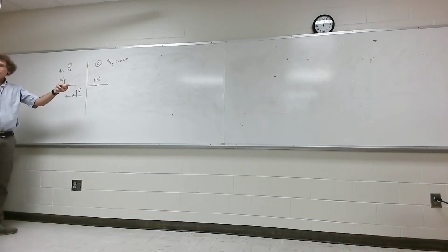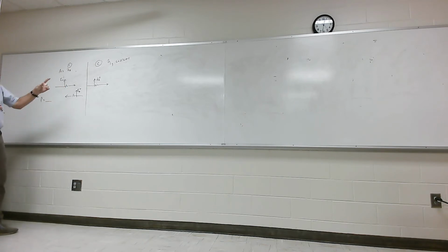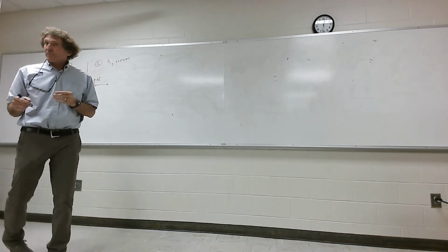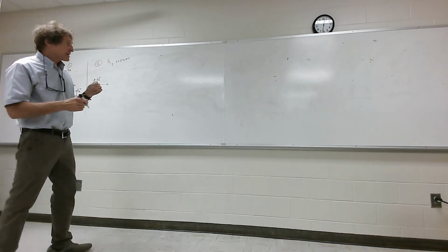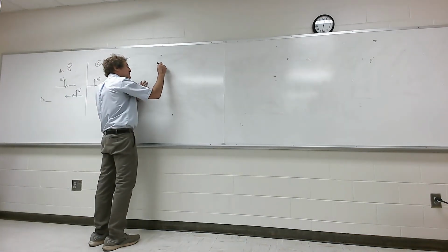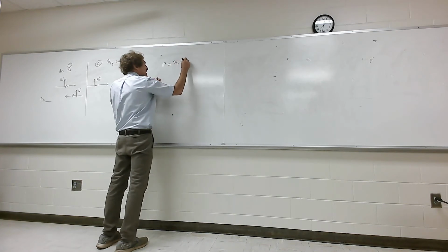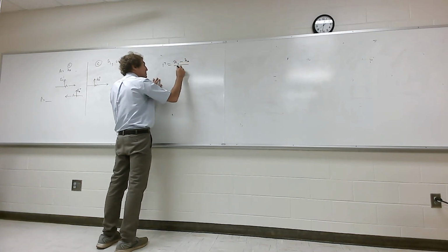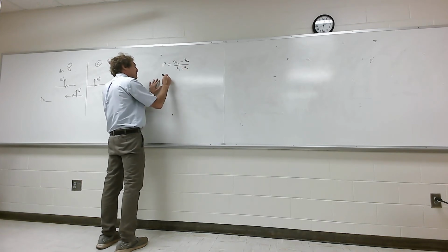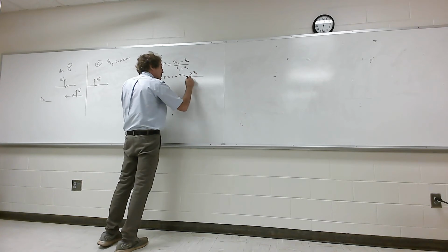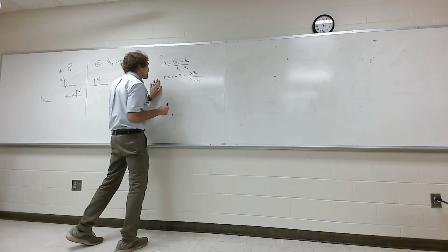I could have that z, so to basically fold into Wentworth's book's coordinate system. I could do that. But if I asked you for the transmitted and reflected electric field and magnetic field, you should be able to get it, because there's two things you need to do. The reflection coefficient is, in this case I call it, eta 1 minus eta 0 over eta 1 plus eta 0. The transmission coefficient is 1 plus the reflection coefficient, or it's 2 times eta 1 over eta 1 plus eta 0, right?